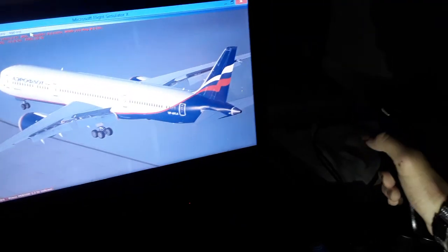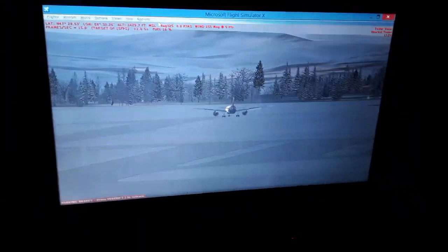So this is the flight controls, the axes that we can use for flying. So I will show you now inside the aircraft how I use the flight controls of the Boeing 787. So I use the control wheel and the control column for climb and descent, the control wheel for making left and right turns, and also the rudder pedals for the yawing turns or the yawing axis.